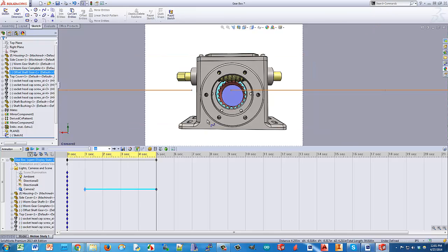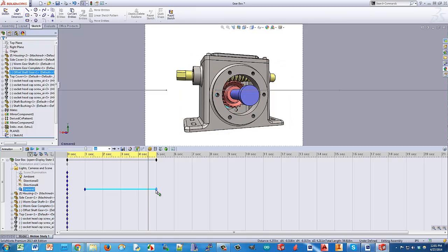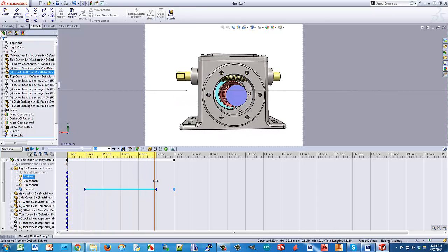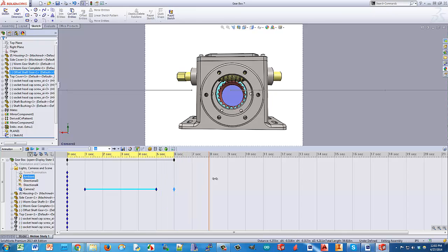So if we wanted to pause it again at the back here, we could hold Control on this key and drag it across. Oops, I don't think that copied both the keys. We only want to do this one. So just select that key and hold it, and now you can see it delays, it does our camera view, delays, and now we can keep going.